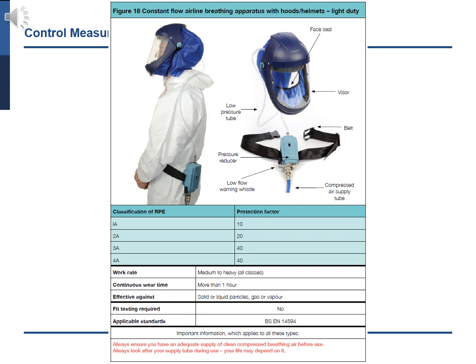Work rate, suitable for medium to heavy tasks across all classes. Continuous wear time, time limited. Effectiveness, effective against solid or liquid particles, gas, or vapor. Standards, complies with BSEN 14594. Important note, ensure you have an adequate supply of clean compressed breathing air before use. Always look after your supply tube, as blocked tubes may lead to suffocation.